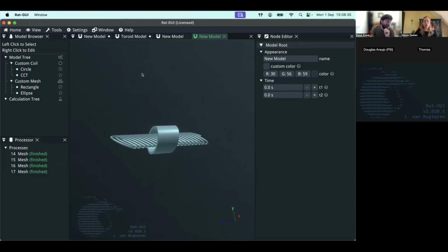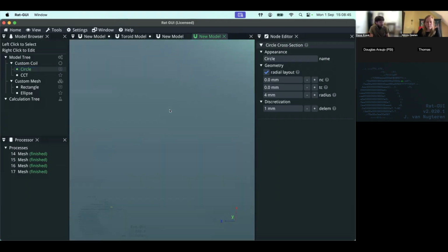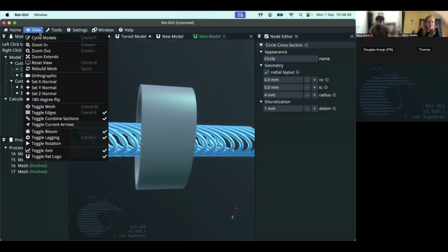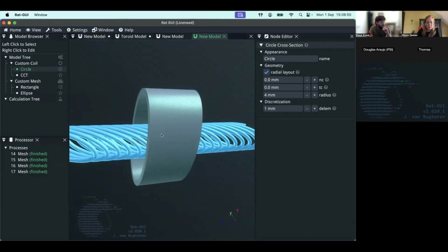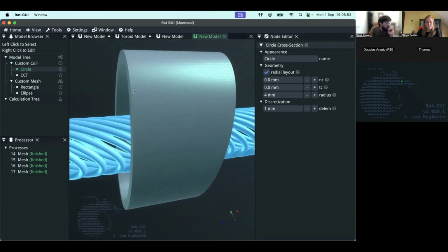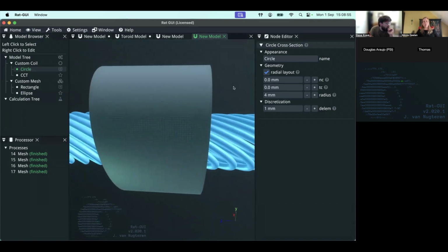Well, that depends on how large your coil is. So the element size will be defined by the number of points in your file. So for like a circle, oh, excuse me, I'm zooming in too fast. I'm going to toggle mesh here. This is a bit of a fine mesh. I think you're basically asking how many elements you need to get accurate calculation results? Yeah, I guess if it sets your mesh size by the number of points, that's pretty straightforward, and I could work off of that. I just don't want to end up dumping a coil geometry that's kind of weird.